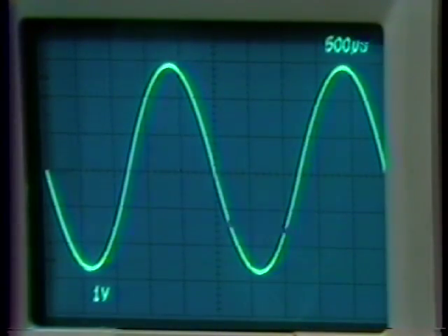That says that we would get into the nonlinearity at an input signal level of 6 volts divided by 80, something under 100 millivolts. Our amplitude scale here is a volt per division, so we're getting nearly 3 volts peak at the input. Clearly we're driving the nonlinear element through its linear region on a very small fraction of the signal applied to it.